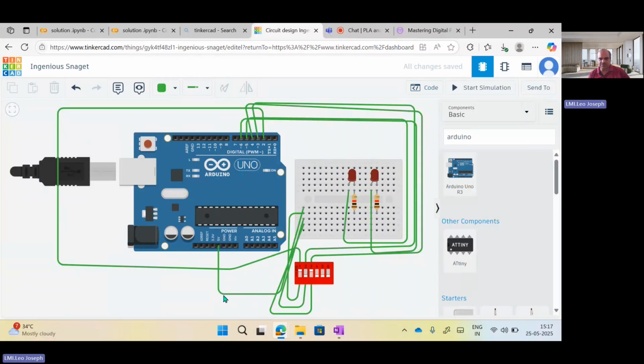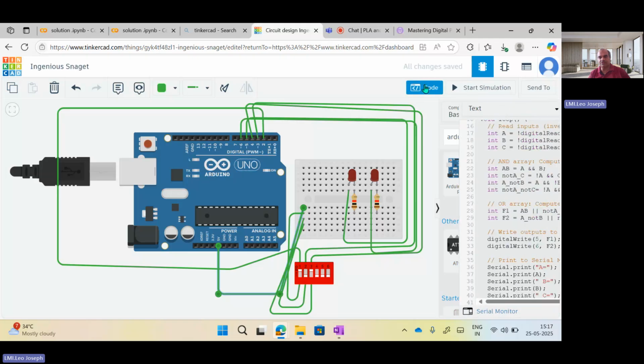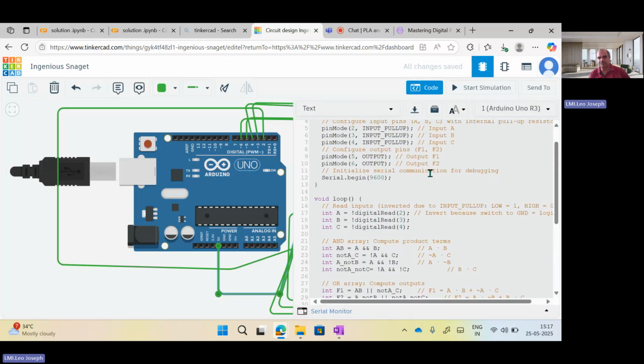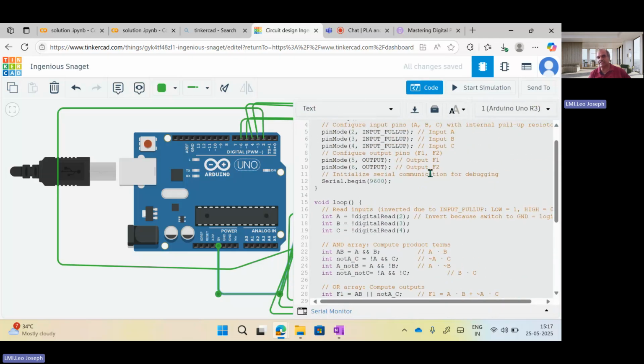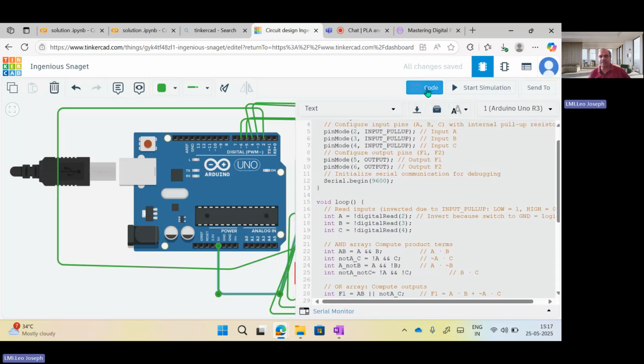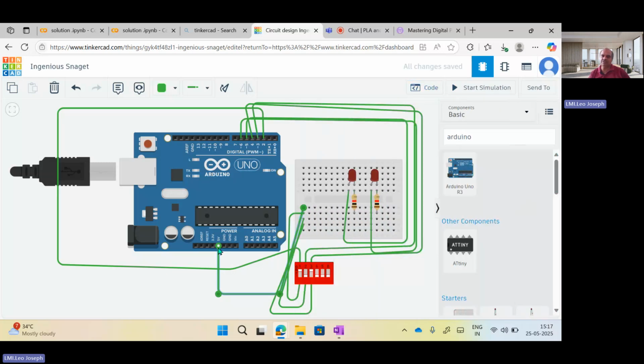Okay, so this ground, for this purpose I am going to explain you one important concept. Remember, this 5 volt, if we are not using pull up in the code, we have shown you one concept called pull up. That means initially it is connected to which point, 5 volts already internally connected. So again if we give 5 volt, it will give reverse result.